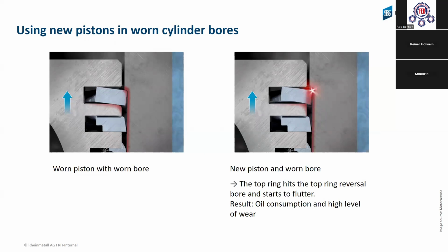When the piston ring has contact, it will lose pressure, because it will vibrate. In this situation, they have no tension and will not seal, and then the oil can jump very easily up to the combustion area. And then we speak about fuel consumption.